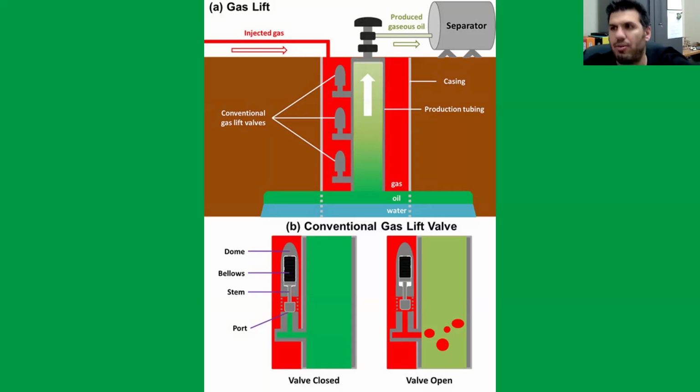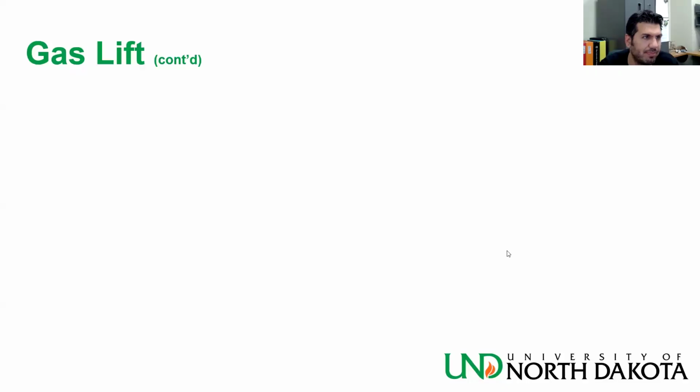Now, this is often considered an active stimulation method because you change the type of oil present, and obviously it will have to be cleaned up and then maybe circulated back downhole or sold to the nearby pipeline, if there is a nearby pipeline, or just flared.